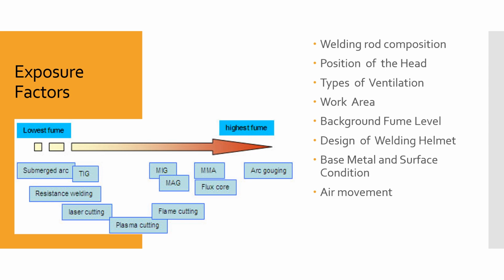There are some welding hoods that have a little belt that goes with them and a hose, with a little filtration system around your waist. It's like a little fanny pack on a belt, with a little battery powered fan. It filters the air and sends it up through your helmet with positive pressure, so there's almost no way the welding fumes can infiltrate your helmet, because there's a flow of air blowing out of the helmet.